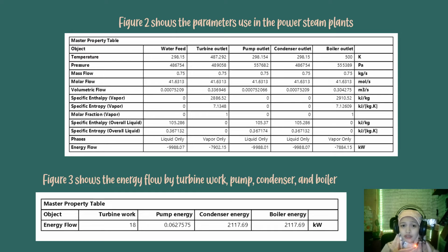Given a fixed set of initial steam parameters as shown in figure 2, lowering the final steam parameter creates a larger temperature difference between the steam temperature and the temperature of the condenser, thus lifting the theoretical efficiency threshold for the thermal power plant. Changes in pressure, temperature and flow rate at inlet or outlet conditions will affect both the isentropic and the thermal efficiency of the turbine.